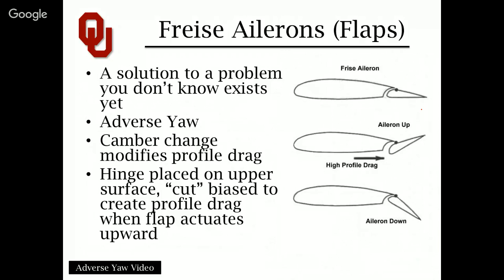So let's say your airplane drops the control surface down, trailing edge down, on the right-hand side of the airplane, the starboard side. Well, drag is now increased on that portion of the aircraft. You're doing this in order to try to roll the airplane to the left to generate what would be called a negative roll rate if you do the right-hand rule out the x-axis leading out the nose of the vehicle.